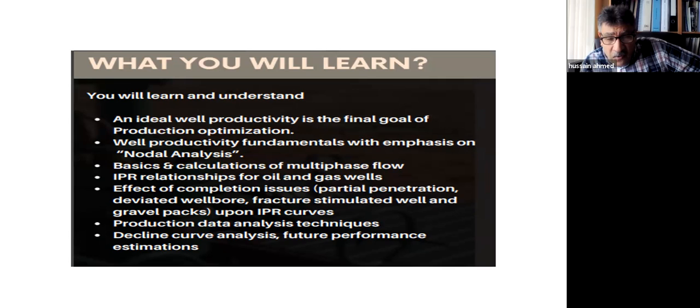Hopefully, if you attend this course with me, we work as a team anyway, because I will talk to you and I will have dialogue with you. You will learn at the end of the day the ideal and perfect productivity optimization. How can I do it? Is it choke size? Is it tubing size? Is it maintaining the wellhead pressure or the PWF? So on optimization, we talk about these factors.